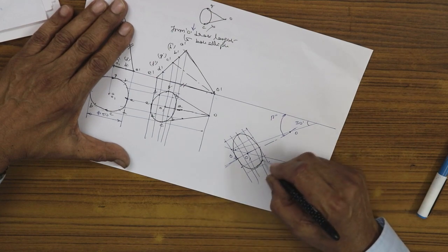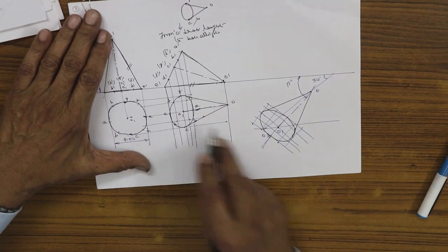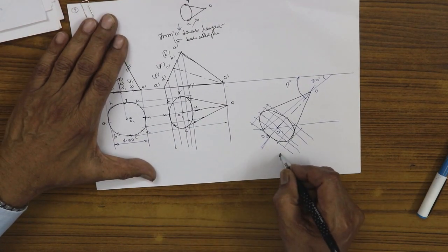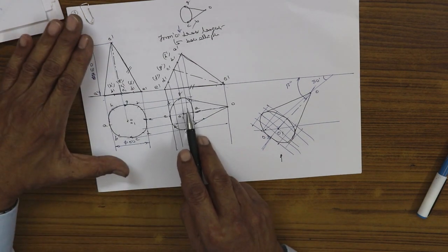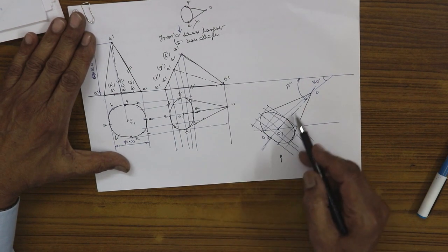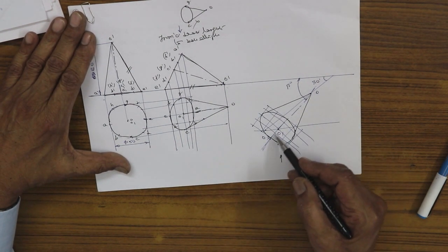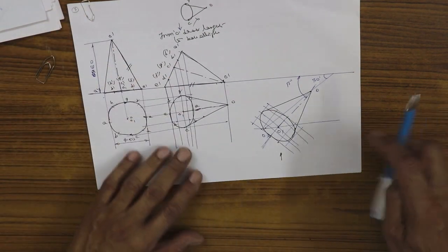From O, you draw here the tangent. Which indicates I reproduce the figure here, projecting at the front view now. Carefully, the entire grid, as we did for the lamina, you reproduce here, get the things done, and project now. So this is the beta angle, the axis is inclined at the beta angle. Project and draw the front view.